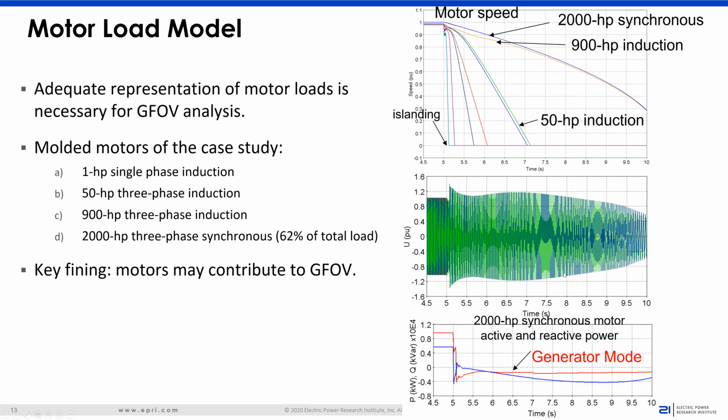The most important regions, so the arrestor, some background: it acts as a nonlinear resistor. The objective is to protect the equipment against surges. At voltages below rated or close to rated, the arrestor acts as essentially an open circuit.